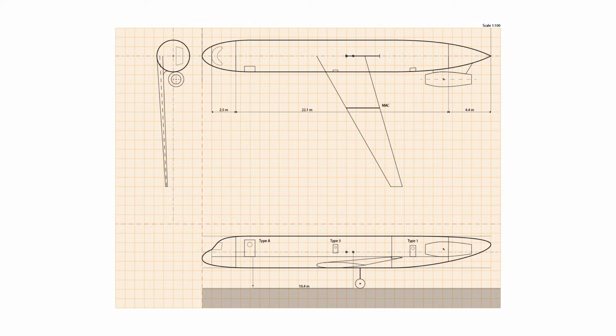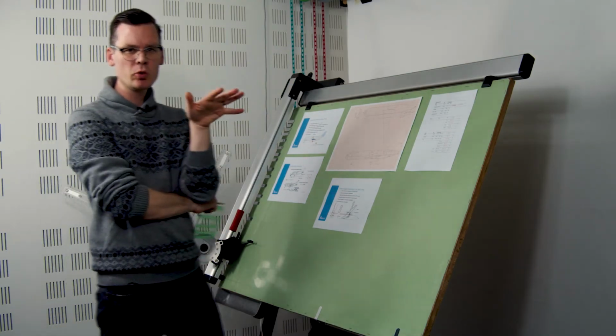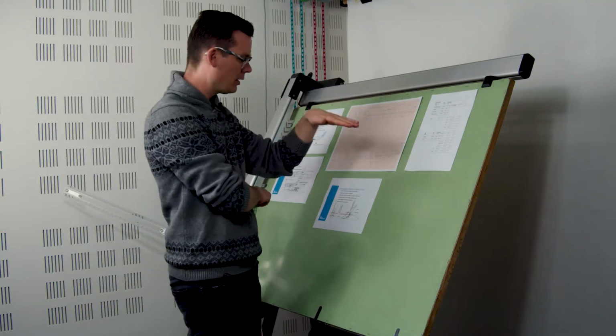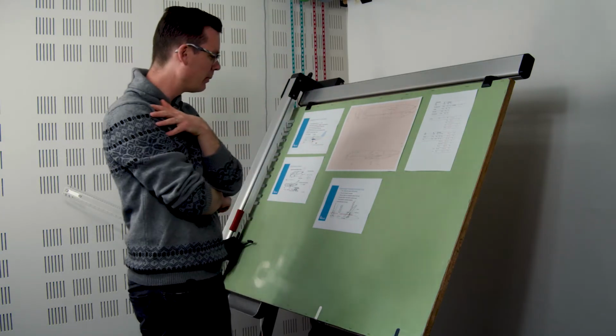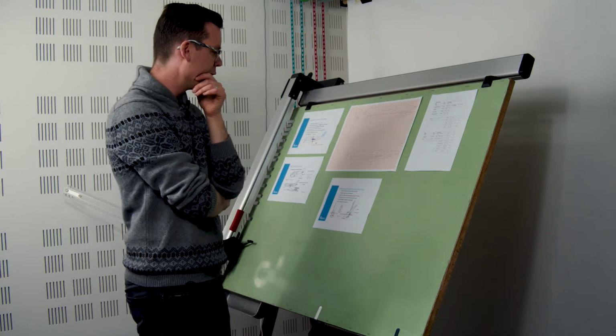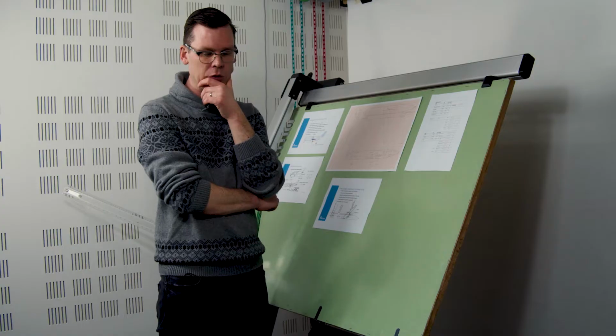And I actually, before, already estimated that the wheel was going to be 60 centimeters in diameter. Now this airplane, when it's on its nose wheel and its main landing gear, is perfectly level. In practice you often see that the airplanes are dipped down a little bit, so the nose wheel strut can then be a little bit shorter. If you want to take that into account, you can.